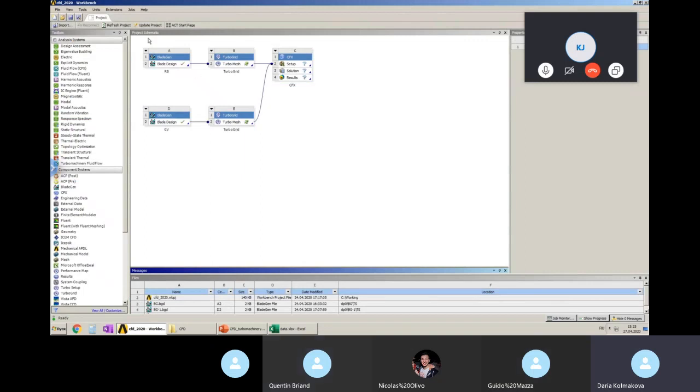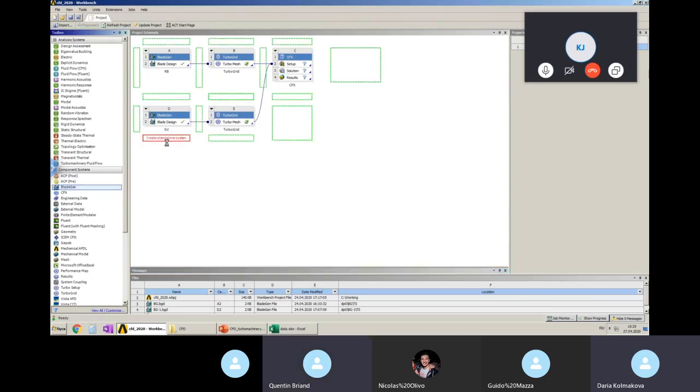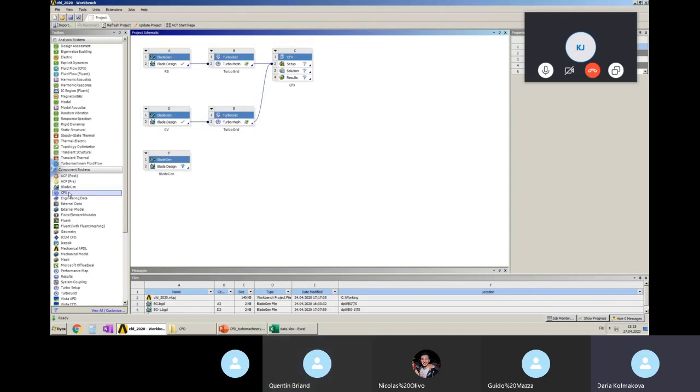Again, the procedure is totally the same. I will not create the whole chain, we'll just use these blade gen parts. So please add these 2 parts in a place that is convenient for you, and give them names like NGV and Rotor Blade.